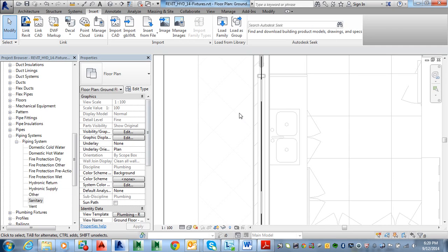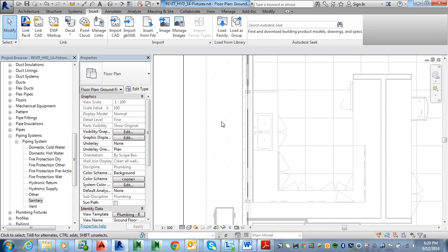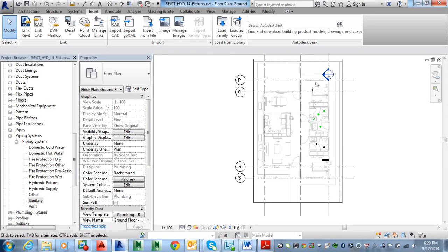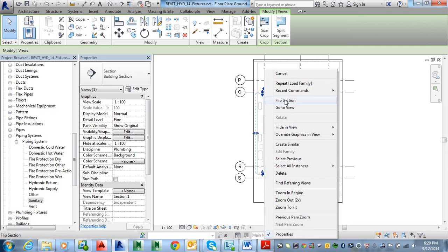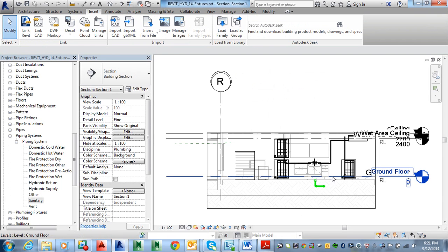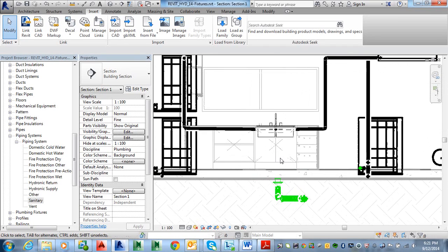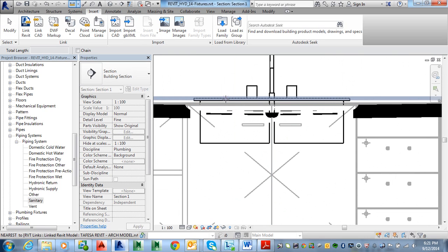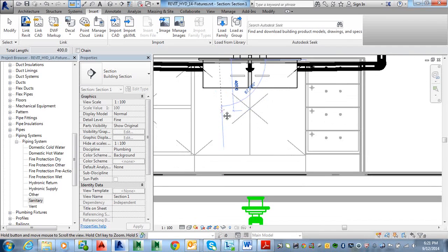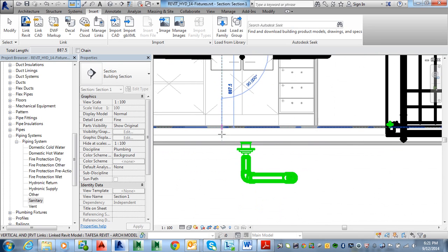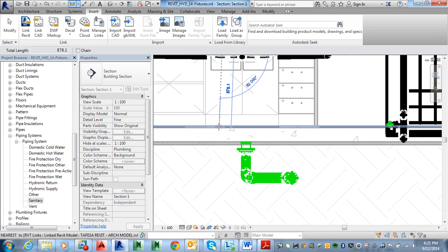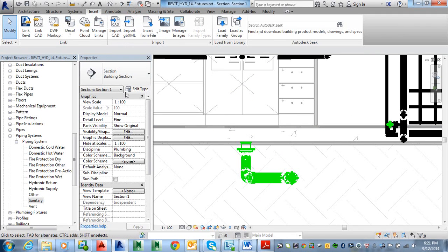I'm just going to check in this section how high that sink is. Just place it around those handles. That's it. So 900 off of the floor level, that's where we'll place our hot and cold water for the sink. And the connection for the dishwasher, we will just put that at, say, 500. Should be fine to connect a dishwasher into.